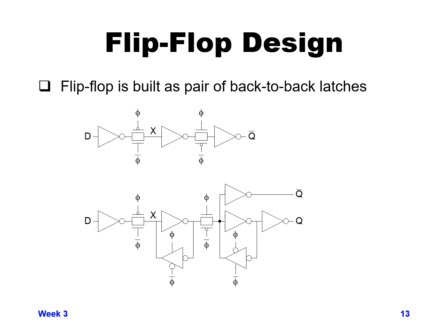The key thing to remember is a flip-flop has a master latch followed by a slave latch, and those are inverted in how they respond to the clock. So this is being done if you look at the clock and clock bar that are going to the pass gates. The front pass gate has the PMOS going to clock and the NMOS going to clock bar. The second pass gate has the PMOS on the bottom going to clock bar and the NMOS going to clock.